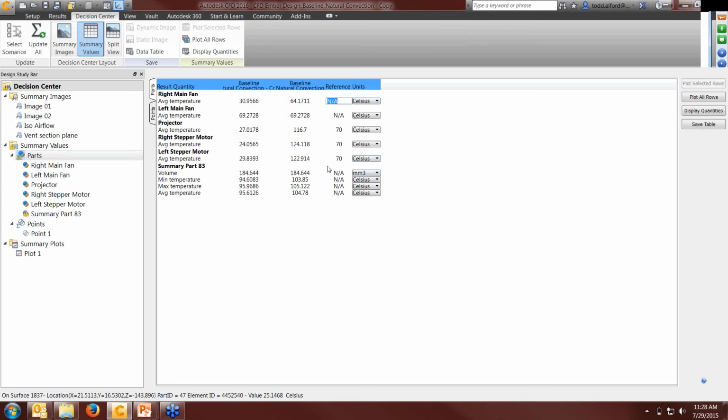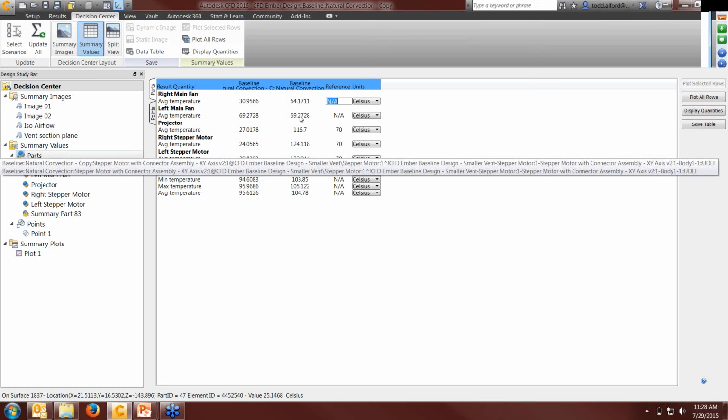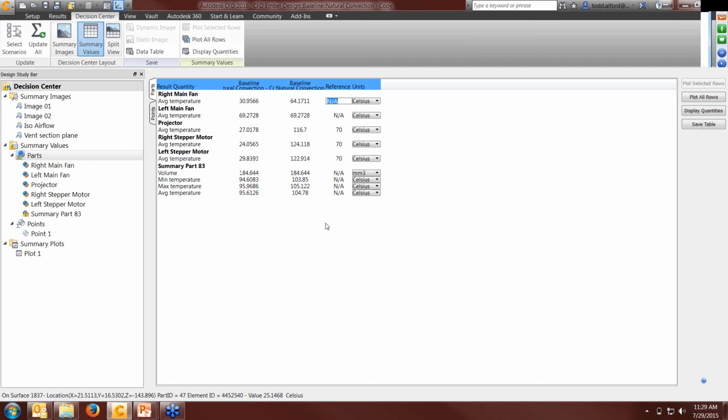And here as we're looking at my models, something went real screwy, and that's probably because I was clicking around and changed a few of these parts. But I know when I was looking at a couple of them, I had dropped the temperature. Basically, I made it a forced flow instead of having it driven by natural convection. When we had it based on natural convection, I had really high temperatures that were probably going to be problematic if I'm breaking 100 C. And I dropped those all to within an operating temperature that would be acceptable.